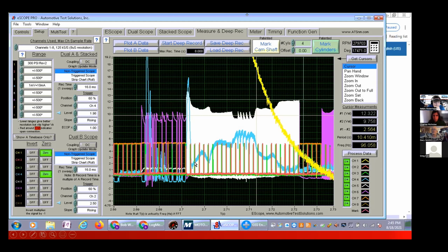Let's identify this, guys, right now for the purpose of this discussion as a shorted phase winding on the white phase alone. Okay. And you can see that occurring because as soon as it turns on, we get a very high current spike and the current keeps rising and rising and rising. Now, after this little ditty here, which we're going to discuss in detail, notice that the current falls and it goes back to normal and it continues to work. You can't see that because the next time the white phase comes on, it's way to the right over here off the screen. This is just a screen capture, guys.